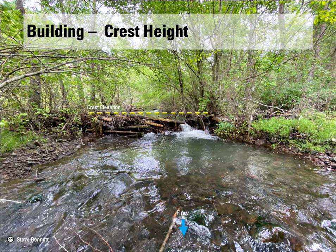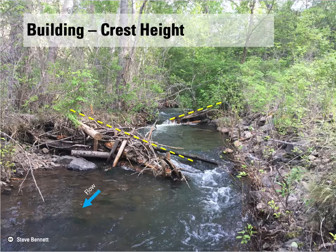Here are some pictures of typical crest height of a bank or channel spanning PAL, showing a slight pour over there, and an irregular crest height. Crest height, and the flatness of it, isn't as important for PALs as it is for BDAs. Here's a photo of bank attached PALs, and we generally slope them down a little bit. It helps to force the water better to the other bank and create that constriction jet.